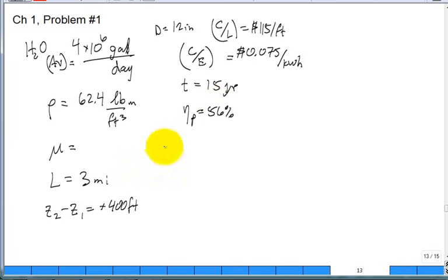We're going to do a modified Bernoulli to account for the power the pump puts in. What form do you want to work in? Head, energy per unit mass, or pressure? Your choice. You can pick one. Okay? Stay with head, elevation like head.